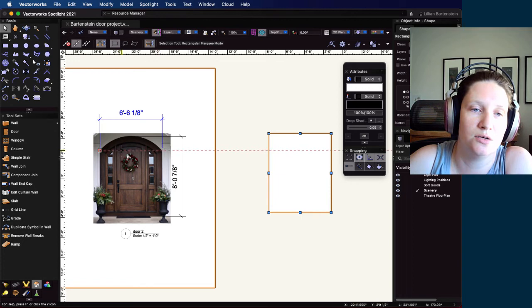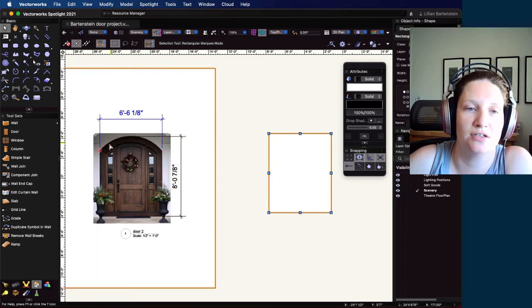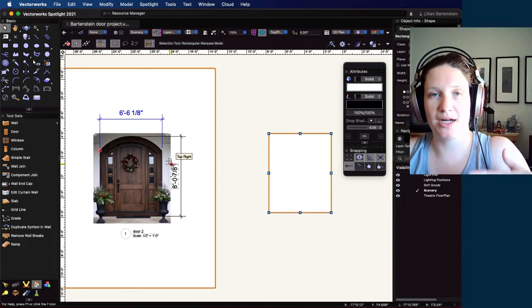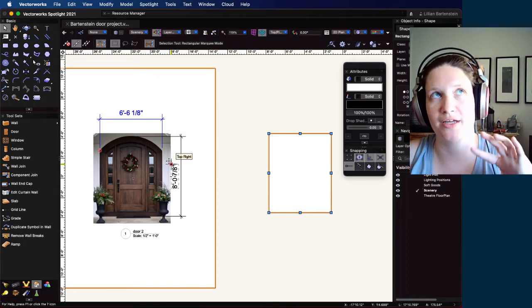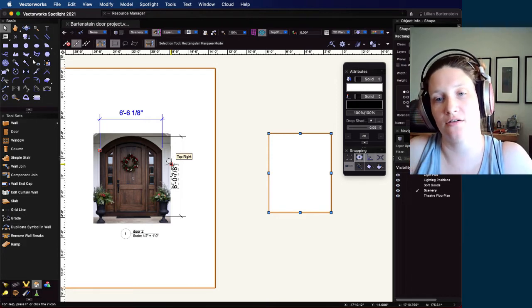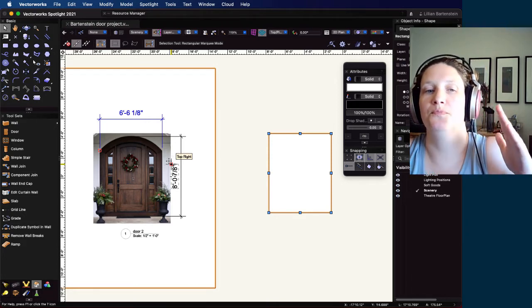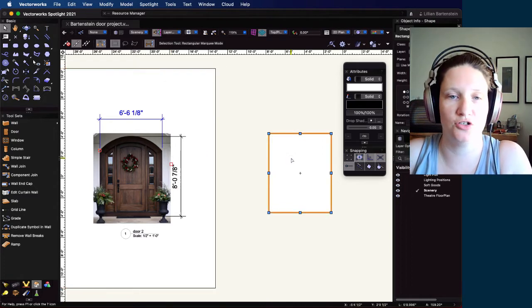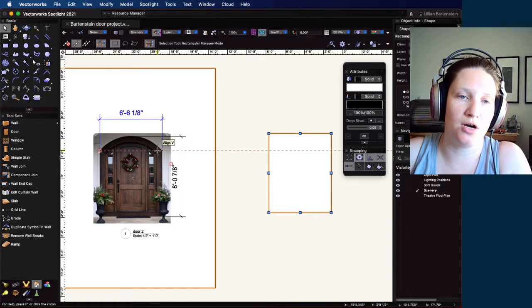So let's start with getting sort of this outside shape drawn, okay? So the first thing I'm going to do, and again, a lot of the time I'll be drawing construction lines. I'll be drawing rectangles that I'll delete later, but they'll help me to get where I'm going as I draw these shapes, okay? So I'm going to go ahead and do this top arc first, and then we'll come in to get these inside pieces, right, for this piece of molding.